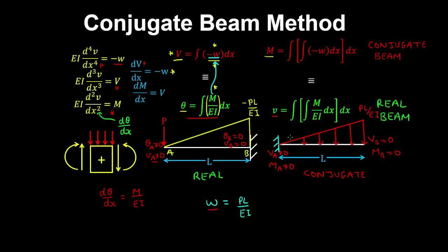And now we can apply simple statics by cutting this beam on the left infinitely close to the support, thereby exposing a shear force and bending moment. And we take the left-hand sign convention, and the resultant acting on this beam, which we'll call FR, is equal to 1/2 by the base of the triangle by the height.